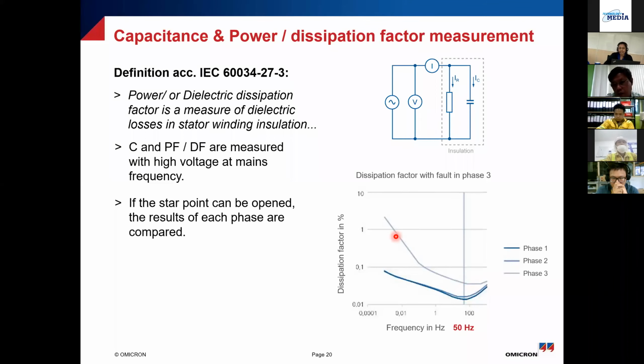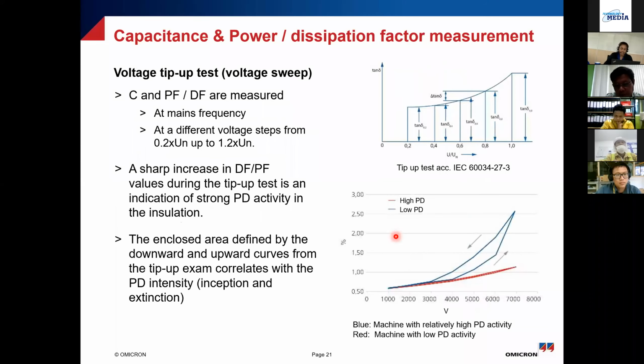So this is a trending criteria. You need to do a trending in order to know if your insulation is deteriorating, and there is no hard pass-fail criteria to it. So no one can say, okay, I mean, it's not as in power transformer. There's no hard pass-fail criteria in here. Even for power transformer in service, they don't give you anything. So in service, it's always a challenge.